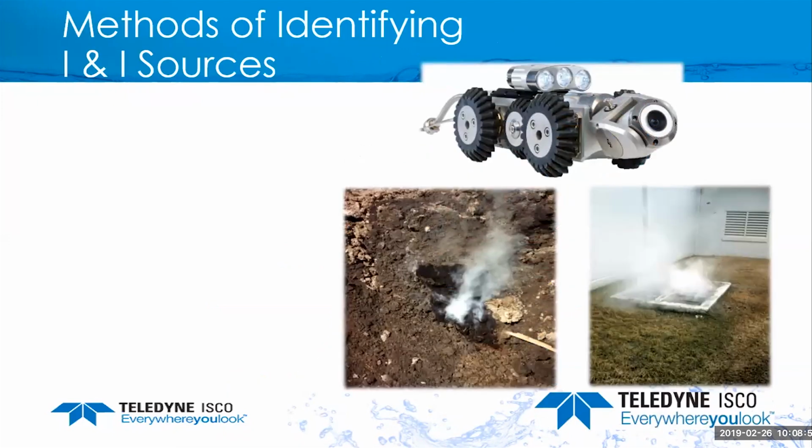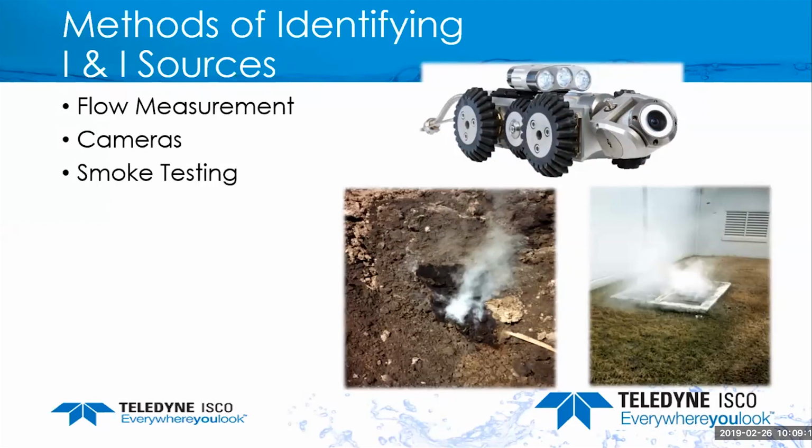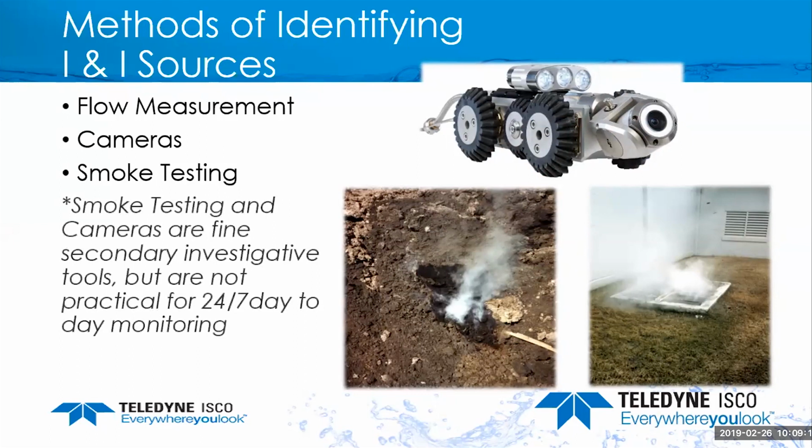So now that we've used a couple different technologies to determine where you may have a problem in your collection system, you could also use cameras to look for problems in the pipes, such as cracked pipes, or you can use smoke testing, and that will help you narrow down where you have a problem.